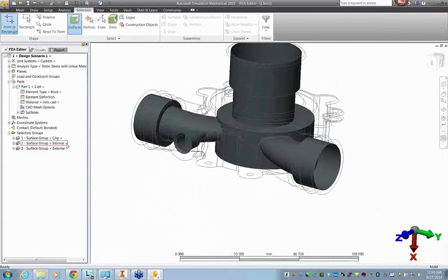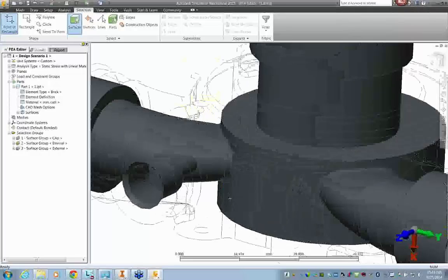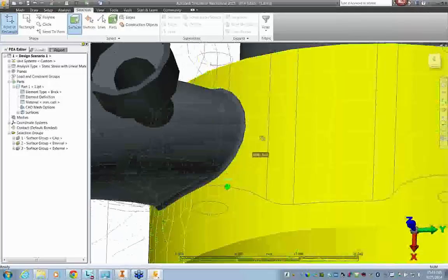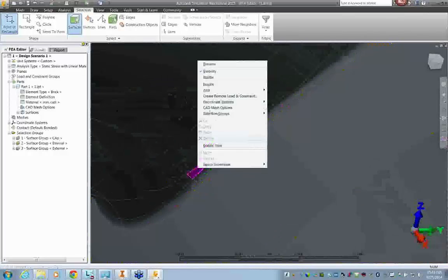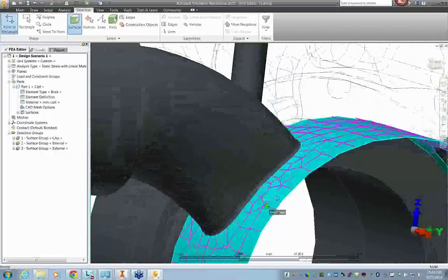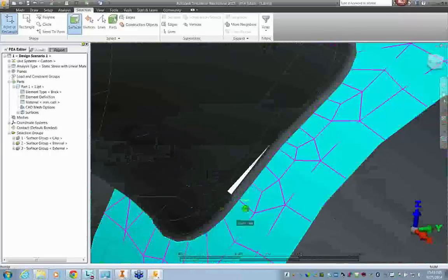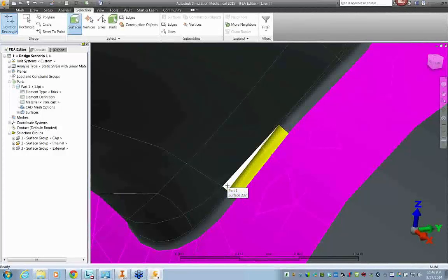And another nice thing is you can see if you missed anything, right? So if you do this work and then you isolate it, you can come in and see if there are any gaps in your selection. In the past, for example, if you forgot to select this little surface, let's hide it, you would have that little visual gap in there that would be very difficult to identify. You didn't select that surface, and then maybe your simulation setup, your application of pressures skipped that surface, so you were actually analyzing this whole analysis with less force than you had to.